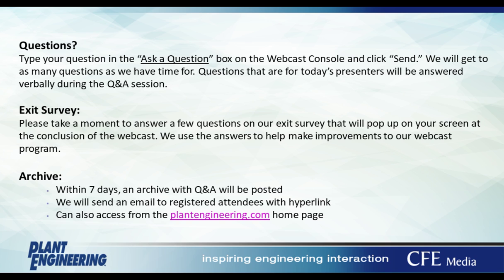Lockout tagout is if somebody actually has to isolate, dissipate the energy, test, do the lockout tagout procedure. I kind of see these things as being unrelated, even though they're in the same equipment, because the safety PLC is for operation. Lockout tagout is for when you're shutting it down to do something. And I have never seen somebody do lockout tagout directly on a PLC, but for sure you're doing it on the motor, or the power that goes to the motor, for example. And yeah, it's controlled by the PLC, but at that point, there's nothing the PLC could do to it anyway because you've locked it out.